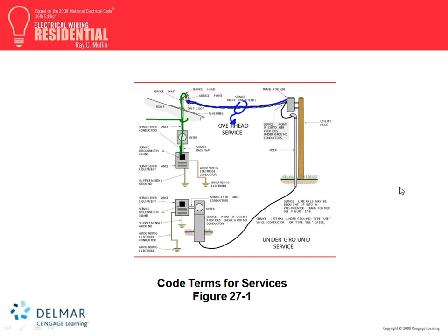And there's one little thing that they do that is not code. Anybody know what they do from here to here that's not code in residential and also commercial sometimes? How many conductors do they first give you? Three conductors. They give you hot and hot and neutral, no ground, because you create your own ground. And how about the neutral? Is the neutral fully grounded that they bring to us? It's not. If you look at the cables that come overhead, it's two fully insulated conductors and one bare conductor, which is that copper or aluminum conductor, the neutral, which is not grounded. That's against everything the code says. The neutral has to be fully grounded. And so the utilities do two things here.